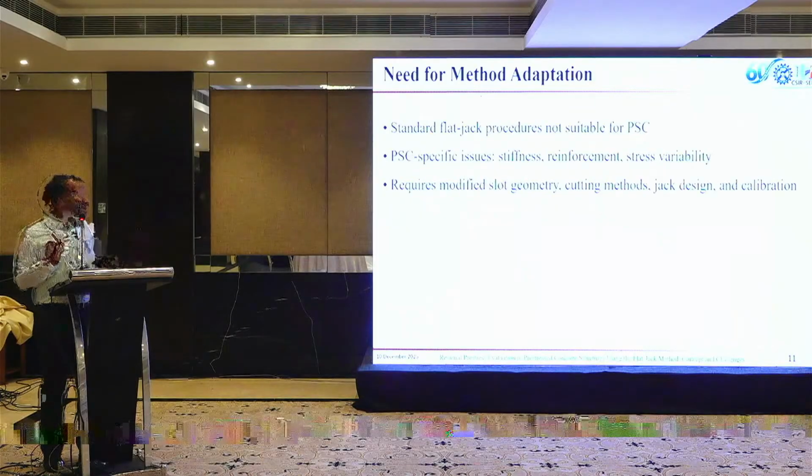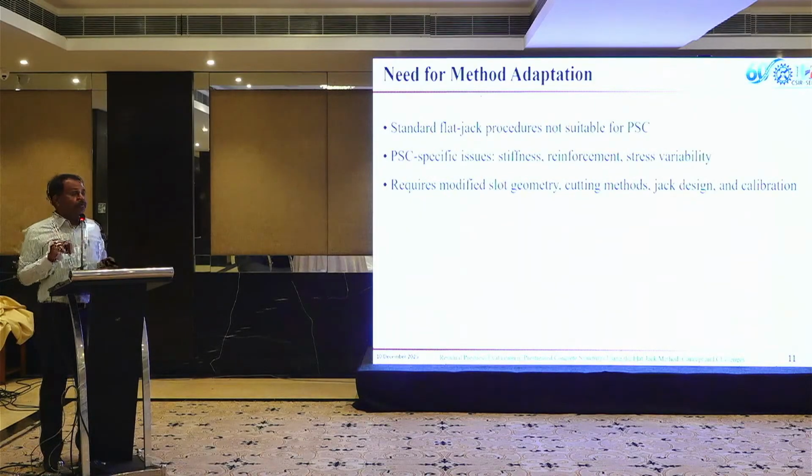at many locations. So the need for method adaptation is that standard flat jack procedures are not suitable for PSC, and specific issues like stiffness and reinforcement require modifications, including the slot geometry, the size of the flat jack, how to cut the slots, and the design and calibration.